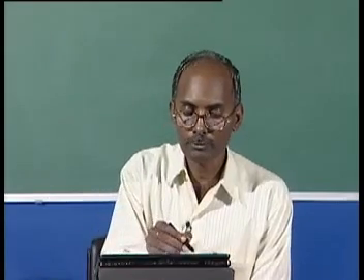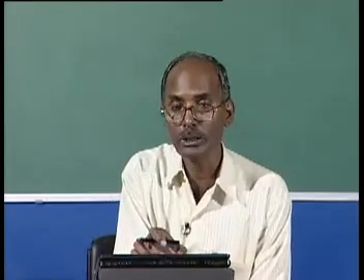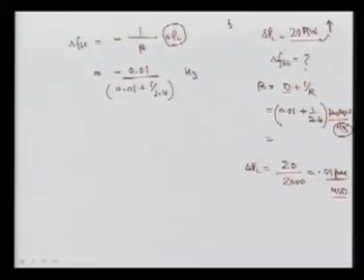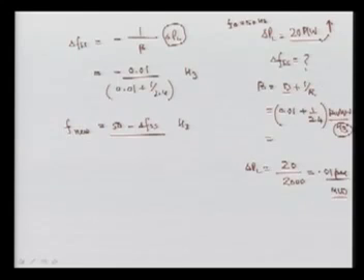So the system frequency change will be this much in magnitude, and we calculated everything; our rated base value was 50 hertz. So your new frequency, F new, will be 50 minus this value, that is the change in Fs, in hertz. So whenever you are increasing the load, your system frequency will fall, and we can calculate it with this.